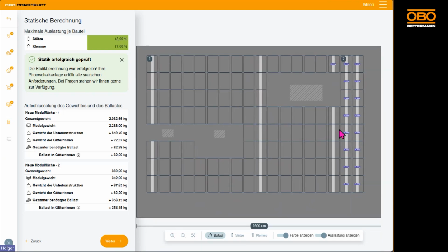The entire load-bearing structure is the roof itself, but since its span exceeds 20 meters, it must be separated in this particular section here. Accordingly, this small section here is depicted, quote unquote, as slightly less favorable due to its specific structural constraints. Then I can correct it again if I wish to. Otherwise, I'll receive here all the detailed partial information for module field 1.